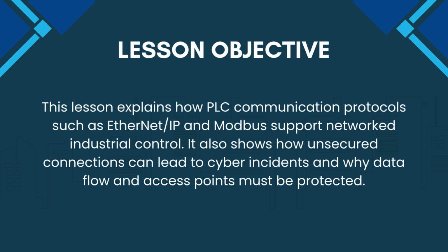Now let's look at the objective for this lesson. This lesson explains how PLC communication protocols such as Ethernet/IP and Modbus support networked industrial control. It also shows how unsecured connections can lead to cyber incidents and why data flow and access points must be protected. As we move through the lesson, keep in mind that communication is essential in modern automation, but those connections must also be secured.